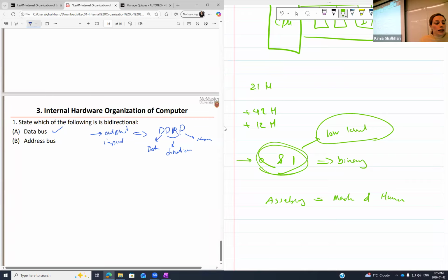Now, if I'm going to turn register P, one more time, this is a good review for tomorrow, DDRP. Suppose I'm going to turn it to output. What would be my command? Yes, ma'am, please. 0xFF. And 0xFF means what in binary? Who can say? Yeah, Nicholas. All ones. All ones means I've got 8 bits, so I have to put 1, 1, 1, 1, 1, 1, 1, 1 in all of my 8 bits to turn it to output.